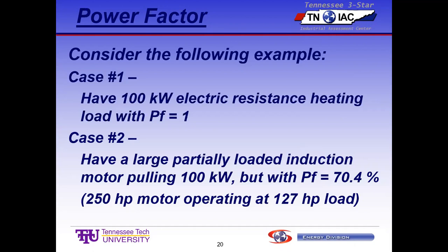Motors get spec'd. Anybody spec'ing a motor doesn't want to burn it up. If you spec it too small, it becomes a crispy critter, and then you get to buy a new one. If you spec it too big, it runs just fine. You may have a low power factor, but most people out there don't even know what that is. So your boss doesn't get very upset about something he doesn't even understand.